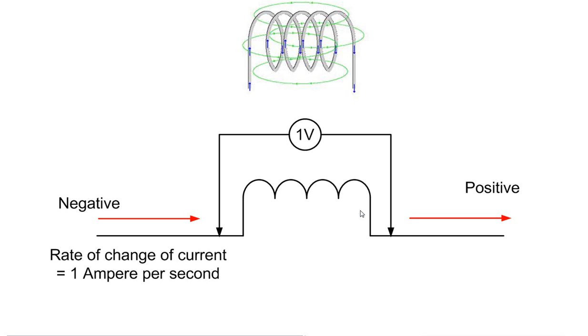That's what inductance is. Just once more in summary, capacitance is that electrical property of a circuit which opposes changes of voltage. Inductance is that electrical property of a circuit which opposes changes of current. That opposition for capacitance is called capacitive reactance, and Xc equals 1 over 2 pi Fc. And that opposition for inductance is called inductive reactance, and XL, inductive reactance, equals 2 pi FL.